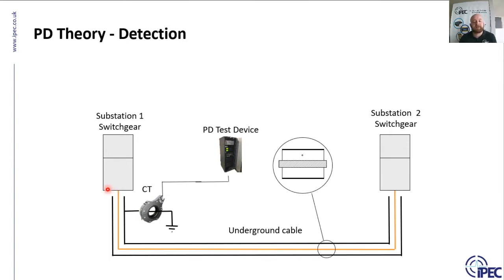You'll be able to detect PD a little bit lower if you install it on the core. However, that's not always possible depending on the makeup. A shutdown is required for that installation, so it tends to be on the core when it comes to a permanent installation or a permanent solution, whereas installing for a temporary application tends to be focused on the earth sheath as well.